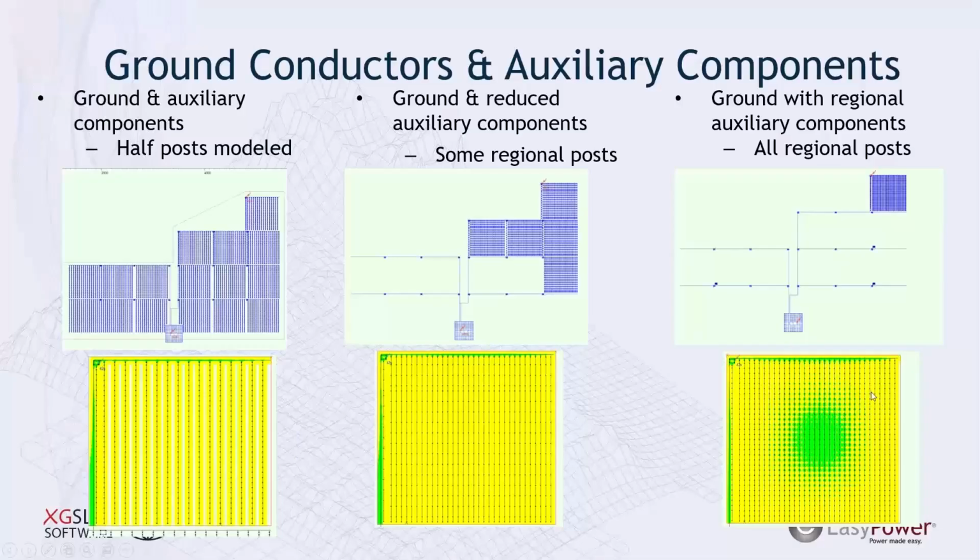When we look at this final model, we have eliminated these other regions that we were previously modeling, but we're doing a higher detail on the region that we're looking at. And what we can see is that we're starting to see more touch voltages that are becoming within compliance. And what I'll press is that, for this particular system, this is going to be the more accurate representation of the real world performance, because we're accounting for all of the components within this region that we're looking at, and we're not seeing the effects, or what will likely be beneficial effects, of these extra portions.